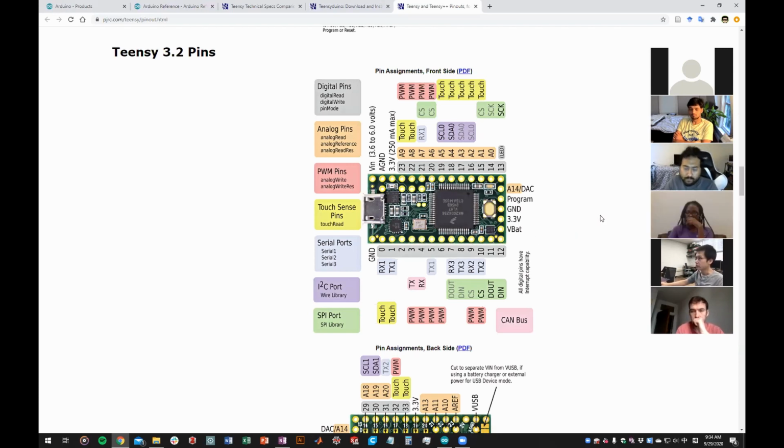But the Zaber controller actually uses RS-232, which is operated at a different voltage. Maybe there are other differences. So that's why we use a serial converter to convert one format of voltage signal to another. That's the little chip we see between the Teensy board and